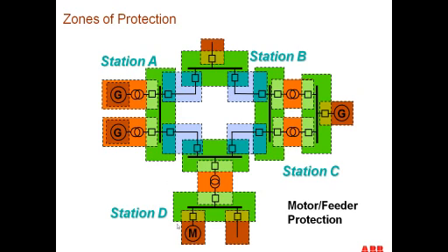And lastly, for motor protection, we overlap our breakers again in our CTs so that our motor protection and feeder protection overlaps the protection for the bus protection we have on the feeders also. So you can see that every stage of the protection, we have overlap between each of our protected zones, so there's no part of the system that has any holes where we don't have any protection involved. Now you may ask yourself, how do we get this overlapping?